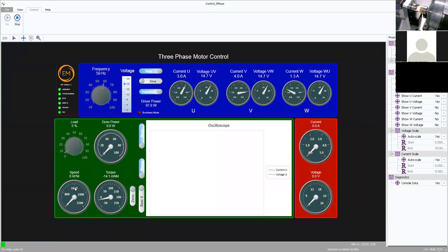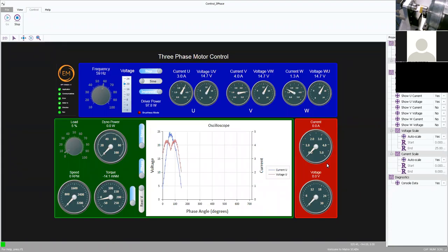There's a speed here. Now bear in mind I've got the locked rotor system in, and there's no speed measurement here. The speed measurement comes with the dynamometer cradle, and there's also a torque reading there. Now on the box there's also a spare current and voltage measurement system.